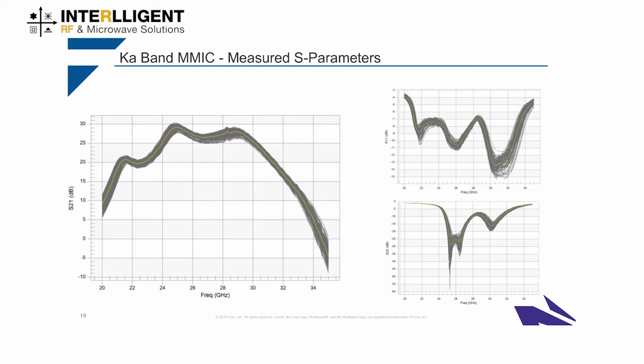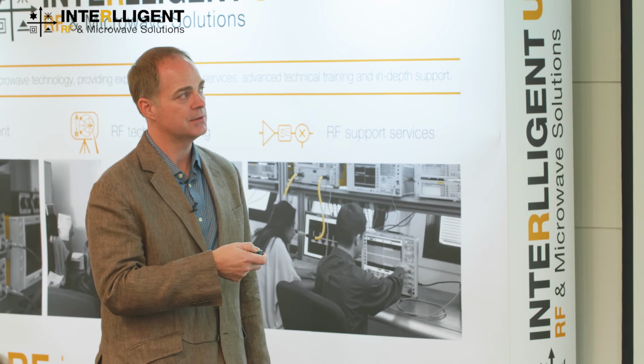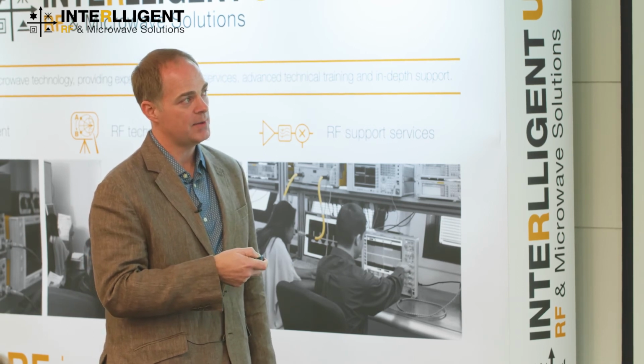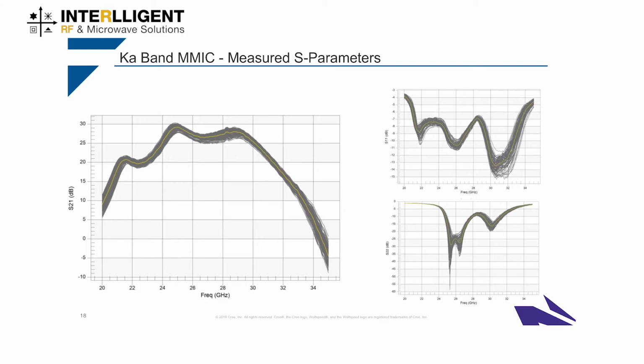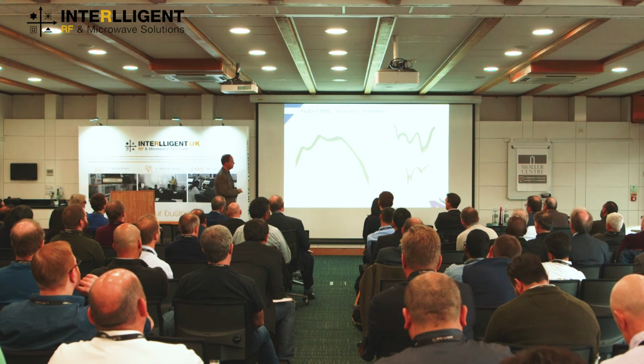So just some results. Small signal. As you can see, we had typically about 27 dB minimum gain through the band. This is actually a representation of one wafer's worth of devices, so you can see a typical spread there in the small signal. And then input and output match. Input match was off a little bit. That's certainly something we'll look at in the design. The bandwidth was correct, but we were seeing some peaking due to loss mismeasurement at up to about -7 dB. And then S22 is certainly good enough, considering it's a power amplifier. Typically these things don't show perfect S22 because you're matching them for power, not for small signal. And the optimal load does change as you drive it up in power.